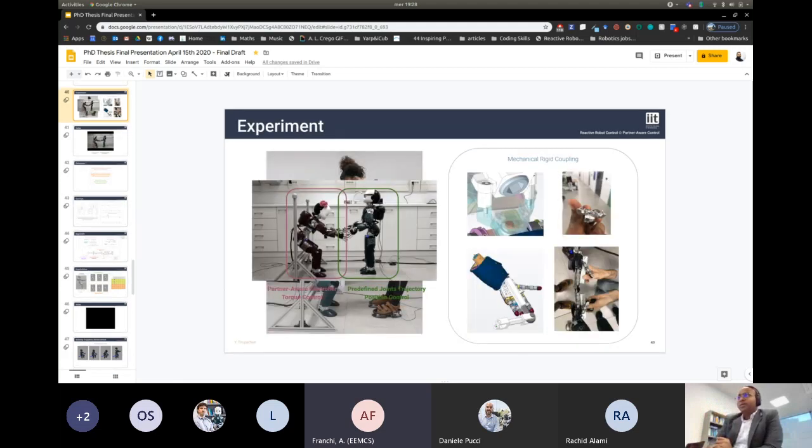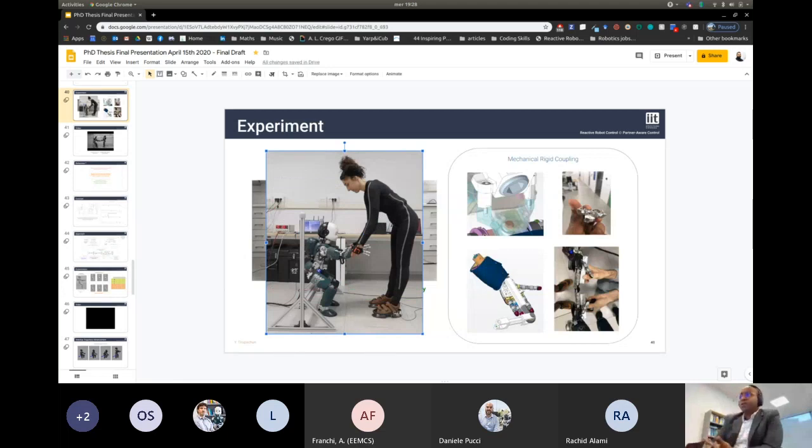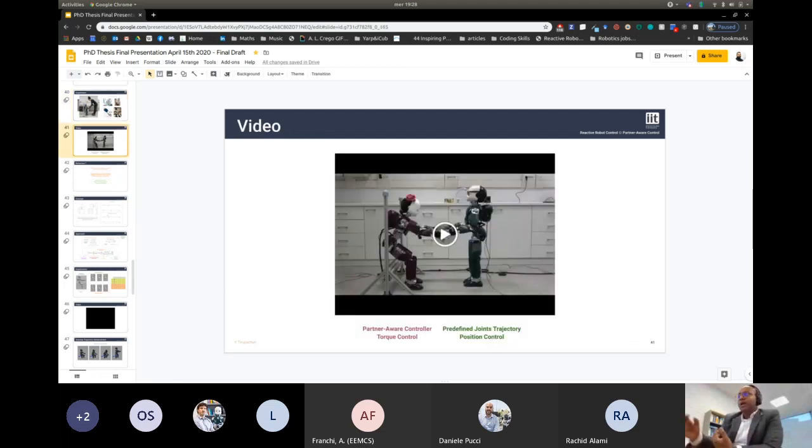The idea here is to actually replicate the experiment of this form, where we consider the human system that is providing all the human quantities in a mathematically similar way for the controller. But at the time of the experiments, we did not have any system for the human in place ready to get all this information for the controller. So we replaced it with another human, which is executing a predefined trajectory for it. But if you try to execute any trajectory in this coupled dynamics formulation for the control torques for the robot which is assisting, it will actually create control loops, if we are using the joint torques of this robot.